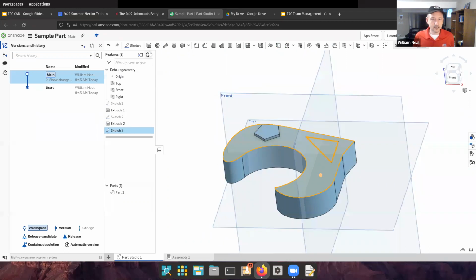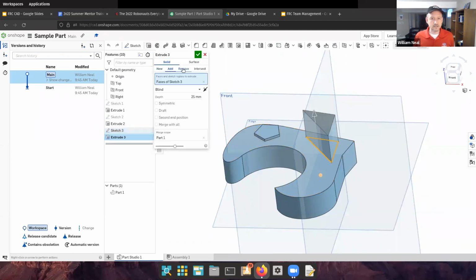So now that it's selected, I'm going to do the extrude, but you see there are a few other features here. I can extrude blindly into the air. I can go up to a next feature or up to a face. So there are various things I can do in my assemblies with different parts to extrude a certain amount, or I can just blindly extrude a certain amount of distance. I can remove the feature. So now it's extruding backwards.